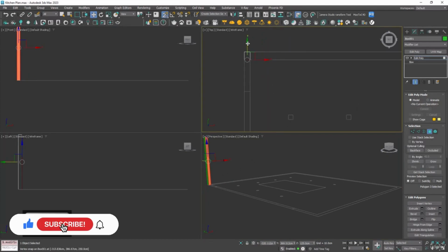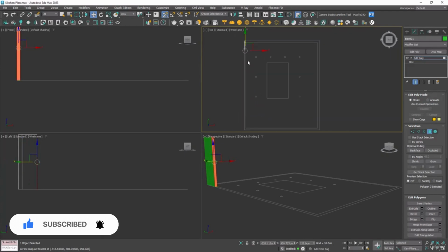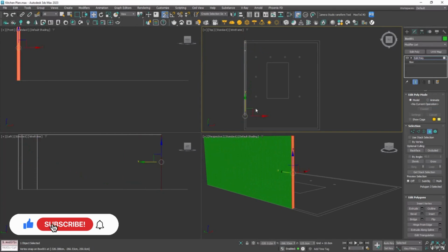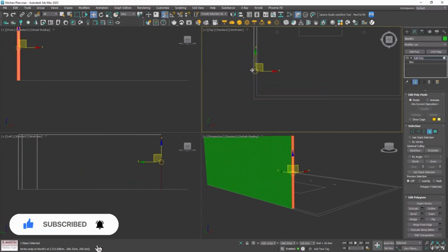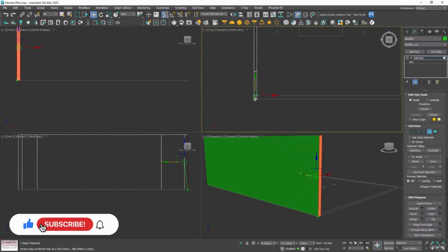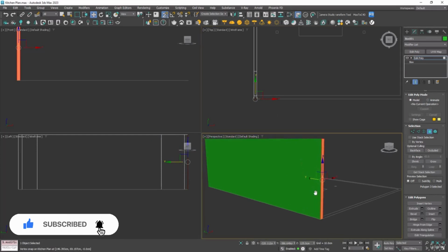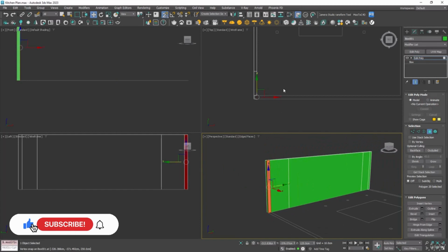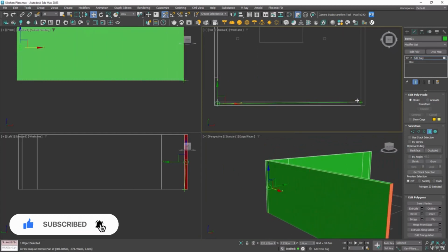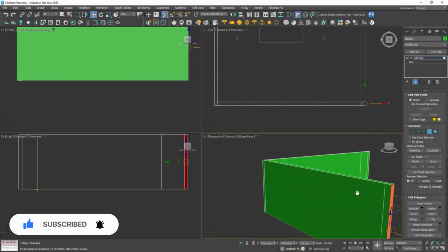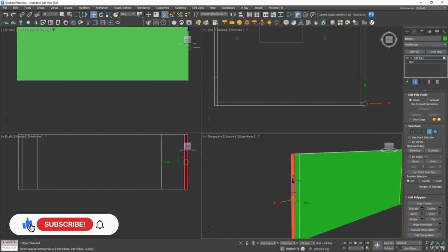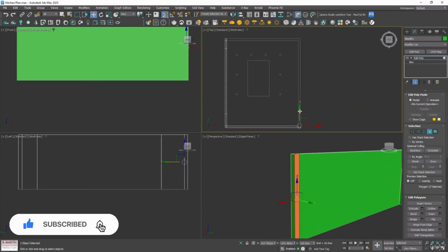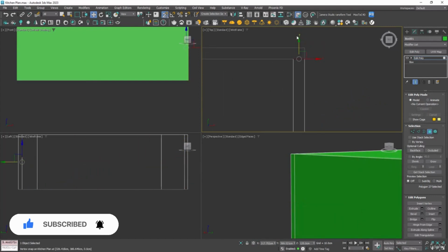I'm going to go to polygon select and select this polygon. And now we can hold Shift, and this means we're using smart extrude, and we can just click and drag and snap this to our floor plans. If you remember the old way of doing this, using Extrude from down here, this would take some time, so this is much quicker. In the perspective view, we can press F4 to turn on wireframes and select that inside face, click and drag, and we're just going to go around all of the walls and use smart extrude to create these.